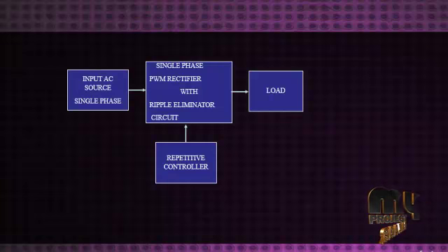Electrolytic capacitors are polarized capacitors whose anode is made of a particular metal on which an insulating oxide layer forms by anodization. Acting as the dielectric of the electrolytic capacitor, a non-solid or solid electrolyte which covers the surface of the oxide layer in principle serves as the second electrode, the cathode, of the capacitor.